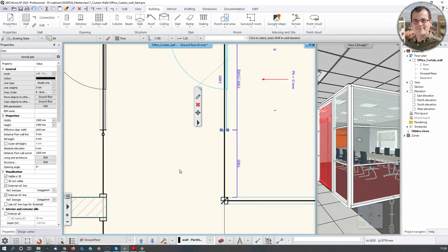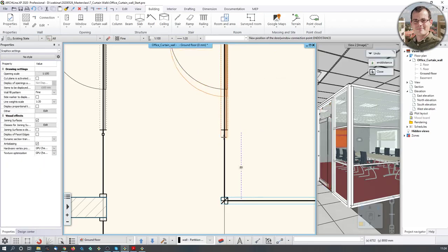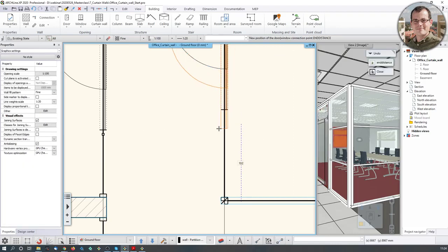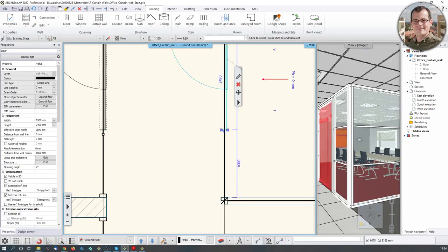And if you have put it and for some reason it's not lining up, you could be even moving it vertically. I mean graphically like that. So you can say that you want to bind to this point. So assume that you made a mistake, assume that it's here. And if you want to move it and align it with another door, just click on the door, say move, hit the shift key and move the cursor to the other door, and then they would be lining up.